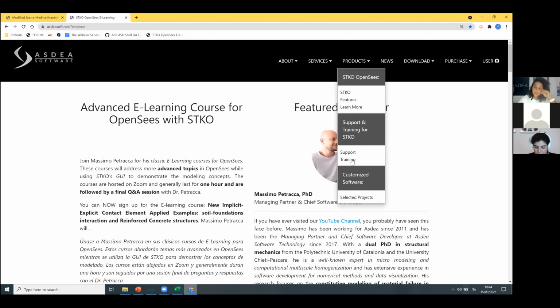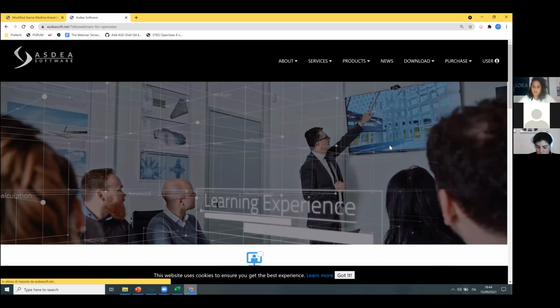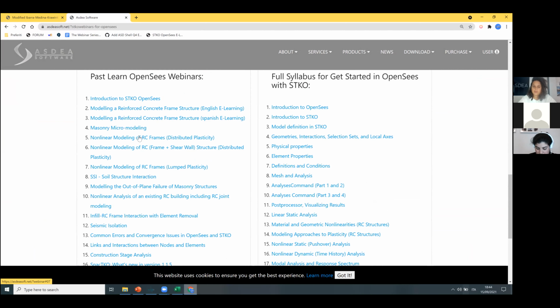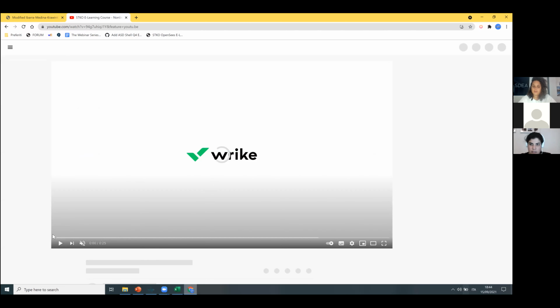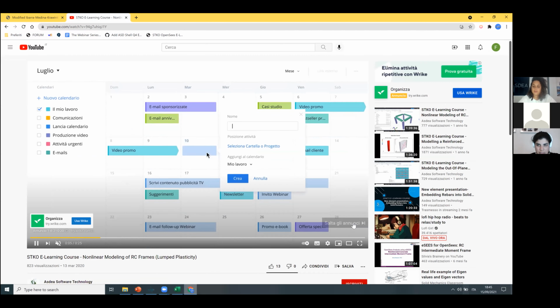Mm-hmm. Then you calibrate the phenomenological law for the spring. Exactly. So I can do this small table and calibrate the phenomenological law for the beam, and then I can do these springs and use this from the really simple one to the big one, right? So the idea is that you want to know how your section behaves in terms of plasticity, no?